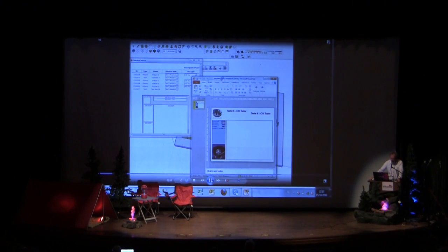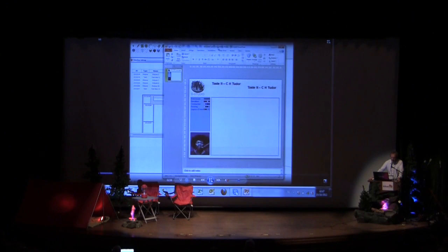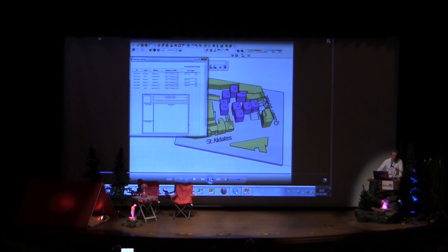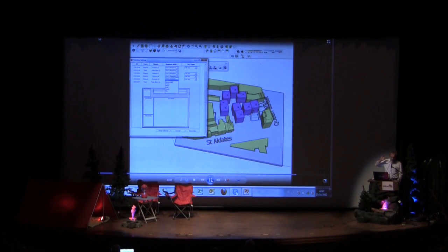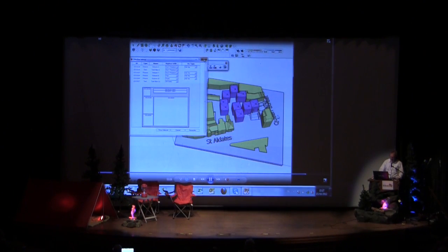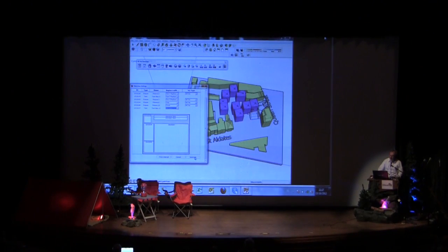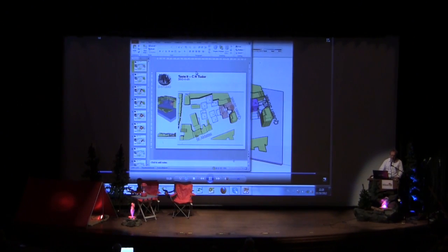In this case, we have a template with some images and some text, and we find in the SketchUp plugin the same layout, and then you can say, okay, I want this view to be replaced by a top view and a front view, etc. Okay, the system goes. Once you define that, you can start the generation, and depending on the project, this would take about a minute to generate.